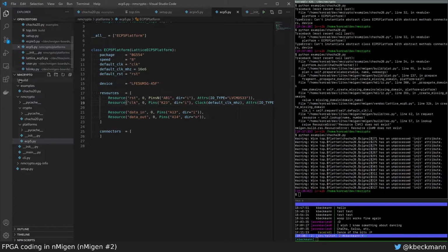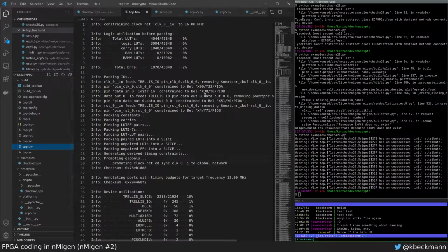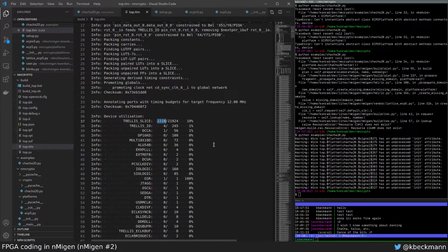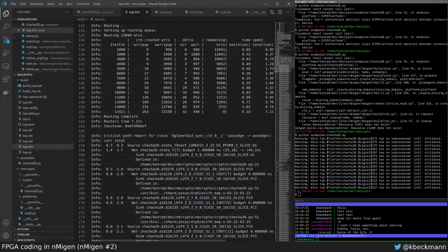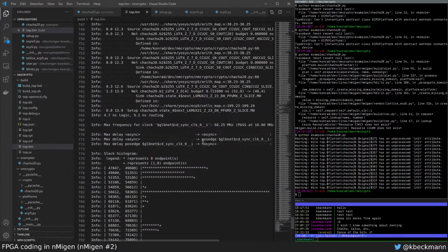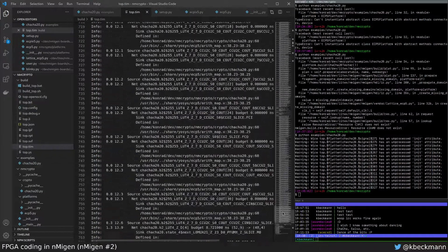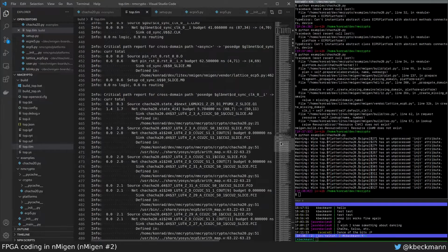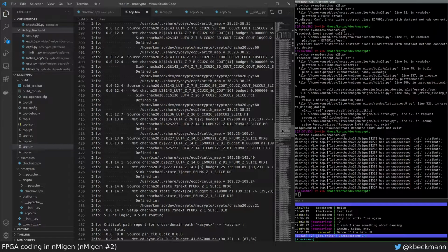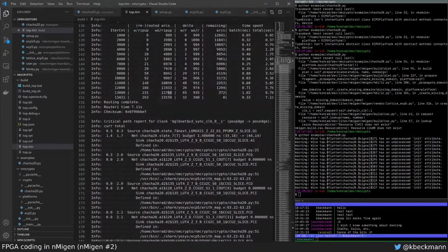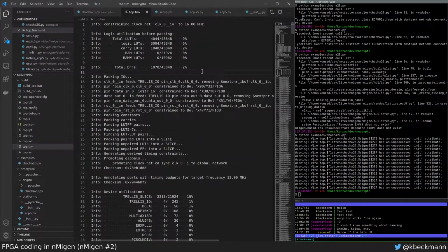Okay, that went slightly faster. So we can look at the timing analysis file to see how many resources we are using. In this case, 2,200, which is, I guess, something. And then you should also get a timing report here, where we can see that we're able to run at 68 megahertz. And this is the longest logic chain that is causing the limitation. So if we would want to run at a faster speed, we can use this information to optimize, basically. So that's cool.